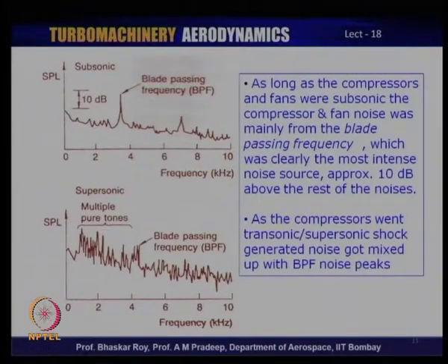Now, what happens, typically in relation to aircraft blades, engine blades, compressor blades, is that certain noise peaks are associated with the blade passing frequency. Now, what happens in a blade passing frequency is that one particular blade, while rotating, passing a particular point in rotation is referred to as the blade passing frequency. It is very easy to calculate that particular blade passing frequency, or blade cutting frequency, and a peak is observed here.